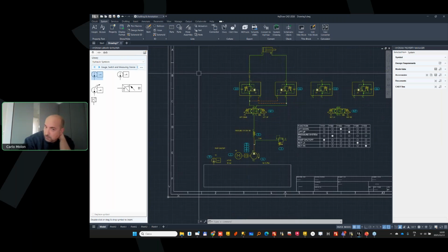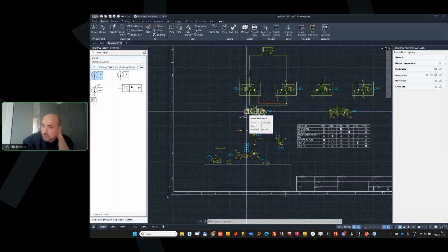So AutoCAD has the ability to create a group of selections. Here we are a bit deviating, I'm going into the details of how I would do it. By creating a group of selection of similar components, spending time once to create a group of selection, it will be easier to renumber those items massively.